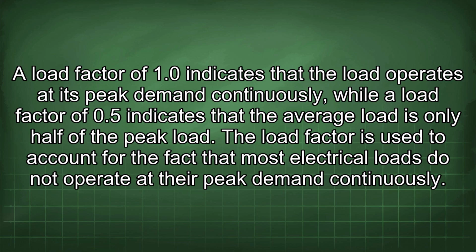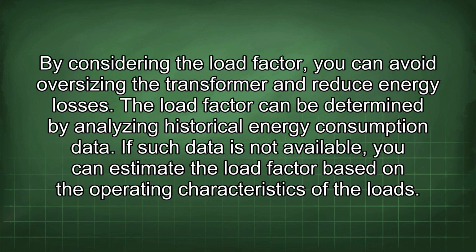The load factor is used to account for the fact that most electrical loads do not operate at their peak demand continuously. By considering the load factor, you can avoid oversizing the transformer and reduce energy losses. The load factor can be determined by analyzing historical energy consumption data.